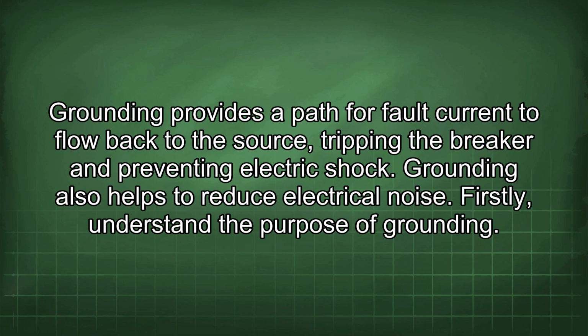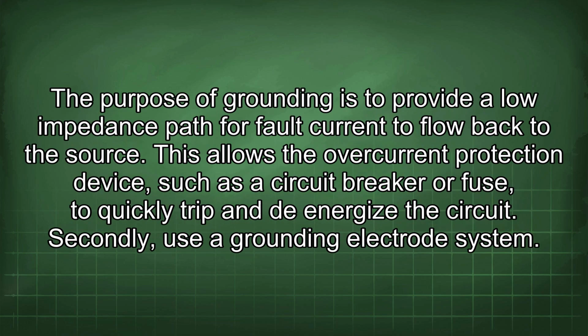Firstly, understand the purpose of grounding. The purpose of grounding is to provide a low impedance path for fault current to flow back to the source. This allows the overcurrent protection device, such as a circuit breaker or fuse, to quickly trip and de-energize the circuit.